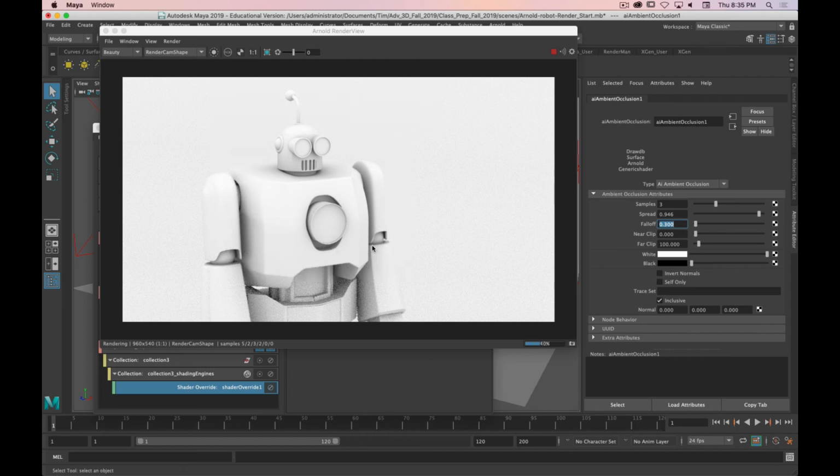Okay, and so once this is done rendering, as with all of these, you can just hit File, you can save the EXR, it just will increase dynamic range. You can also save it as a JPEG, doesn't matter too much for our purposes. Okay. And that's really it. Those are the only additional renders that I wanted to call out today. Then the next video will be about what to do with this ambient occlusion render and the full color render and other things you can do in Photoshop to add that final bit of polish to your still images.